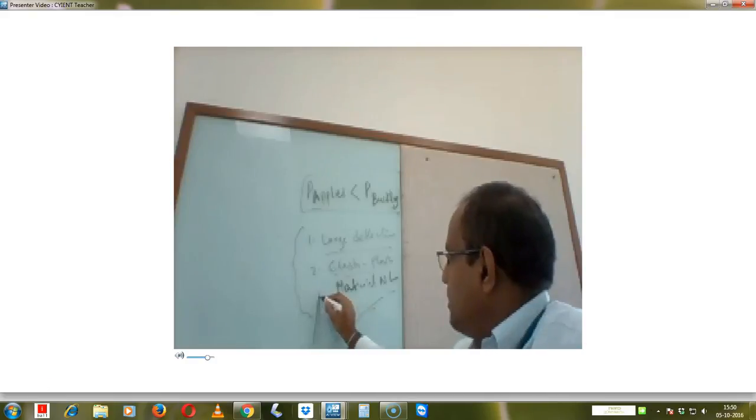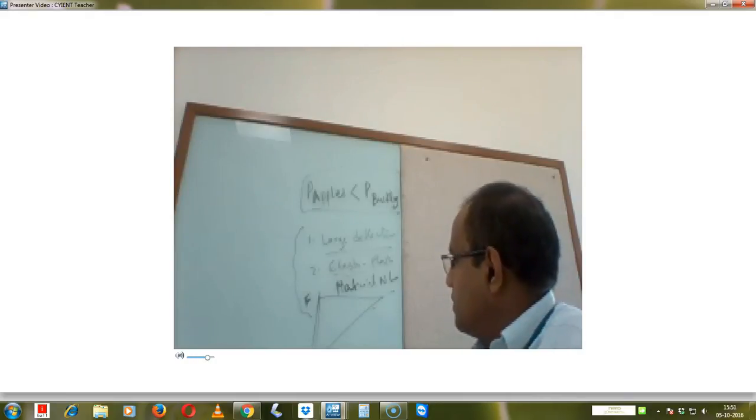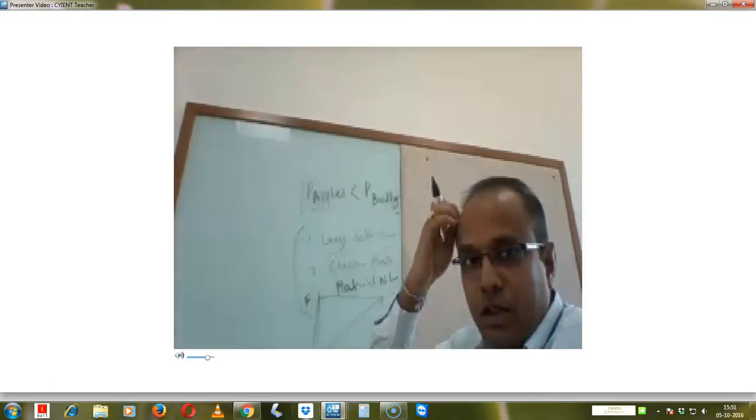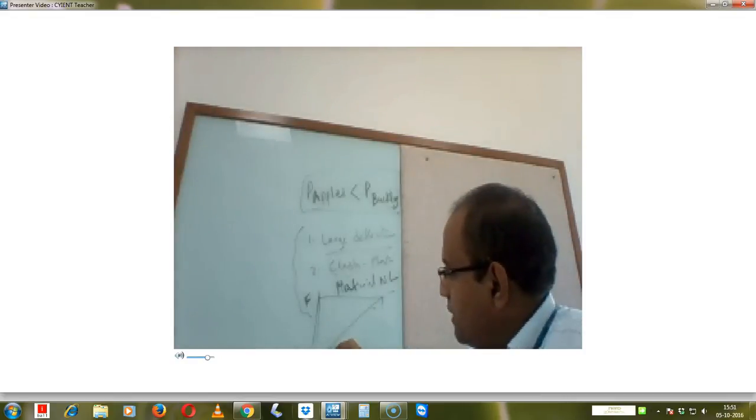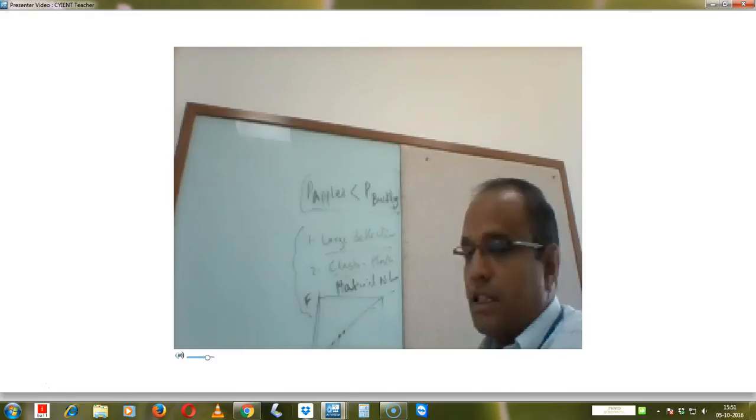So I want to apply load here and that here. Okay, and this is our time, number of substeps, 0 to 1 time. Now, what we need to do in nonlinear buckling analysis is give very tiny substeps. Each substep will try to solve the analysis and get the convergence result. It will solve until a point where divergence will happen.